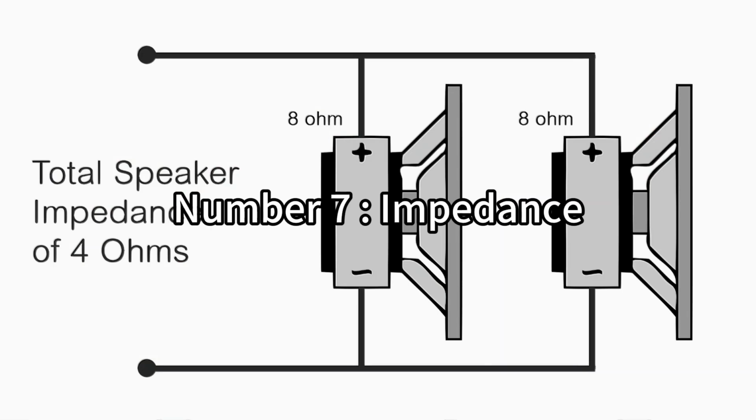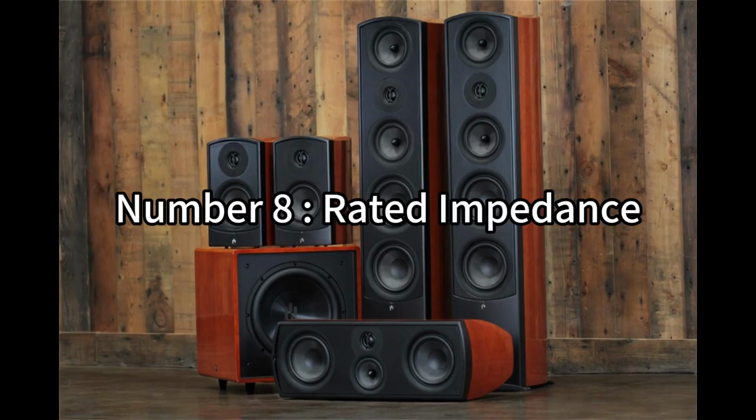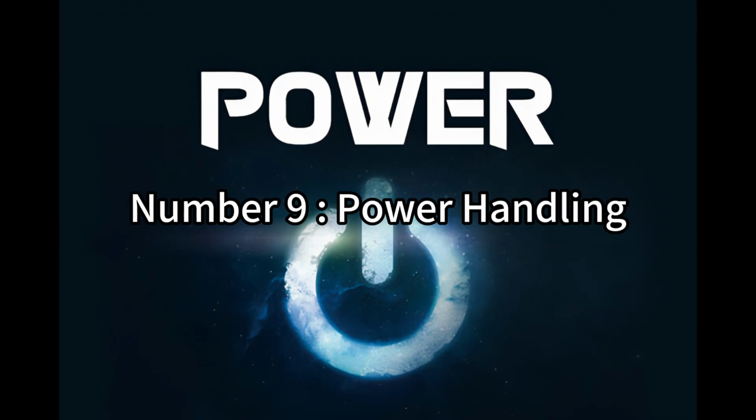Number 7. Impedance. The impedance characteristic curve shows how the electrical impedance of a speaker voice coil varies with frequency. Number 8. Rated impedance. Rated impedance is the minimum value that appears first after the maximum value on the impedance curve, measured in ohms.